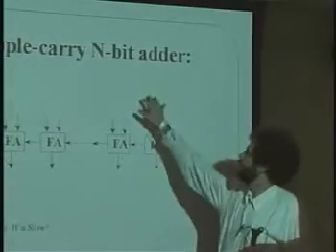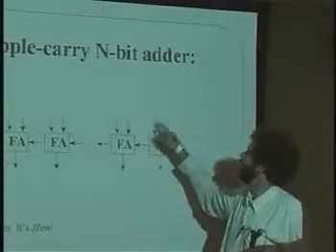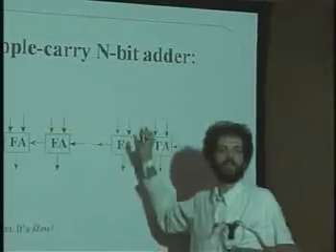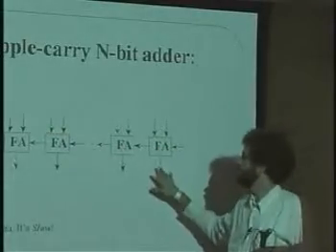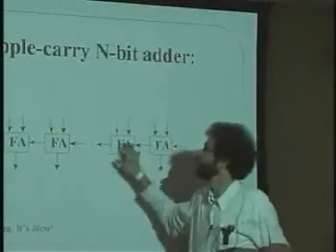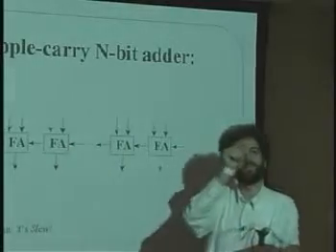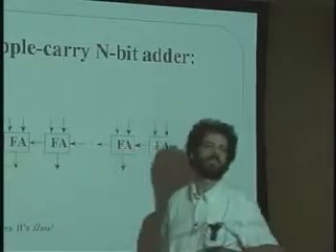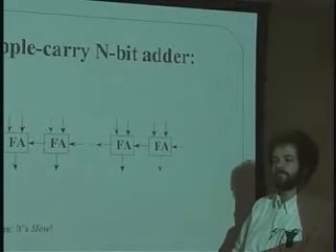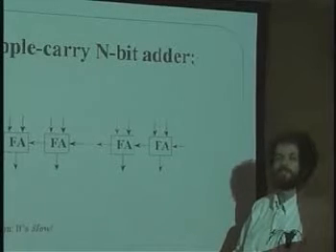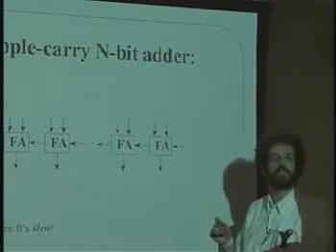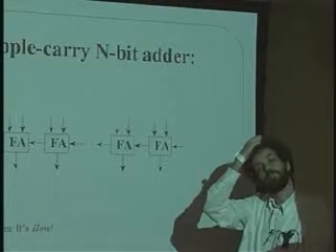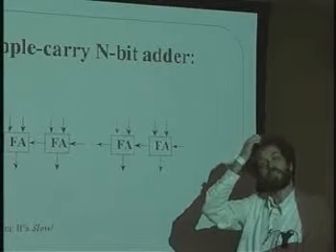And what would the carry-out of the left-hand bit mean? So let's say I fed in 32 bits of A, 1, 2, all the way to 31 and 32, and also B, and I got a 32-bit number out of here, and I had 32 full adder 1-bit slices. Well, what would it mean for the carry-out to be high? Isn't that going to depend on what our sign is? That's absolutely right. So if the numbers are positive and you get a carry out, what does it mean? The number got too big, right?